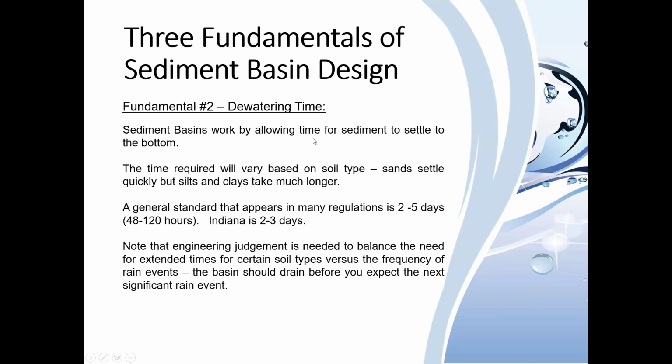The second fundamental is dewatering time. Again, basins work by allowing time for sediment to settle to the bottom. The surface withdrawal takes that cleaner water from near the surface and lets mud settle down, and then drains from the top down. The time required is going to vary on soil type. Obviously, if it's a sandy site, it's going to settle much quicker than if you've got silts and clays. The most common standard is 2 to 5 days as a range of drain time that you can use. The Alabama standard is 2 to 5. Indiana is 2 to 3 days.